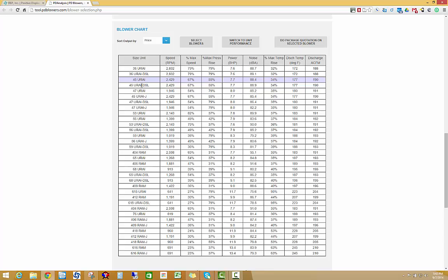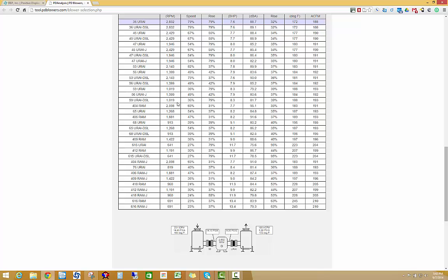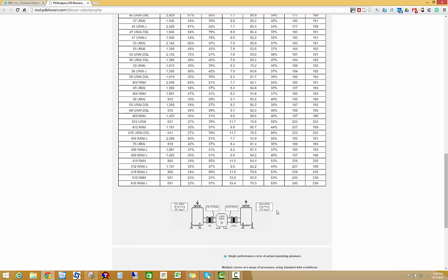You can select different units by just clicking on that particular line, and where that becomes important is down here at the schematic. So based on whichever unit you select, the process conditions change in these blocks. So here we represent 231 ICFM at 14.43 psia and 100 degrees Fahrenheit. So those are your inlet conditions. We've got a 0.3 psi pressure drop that we put in at the top. So at the blower suction point itself, it's at 14.13.